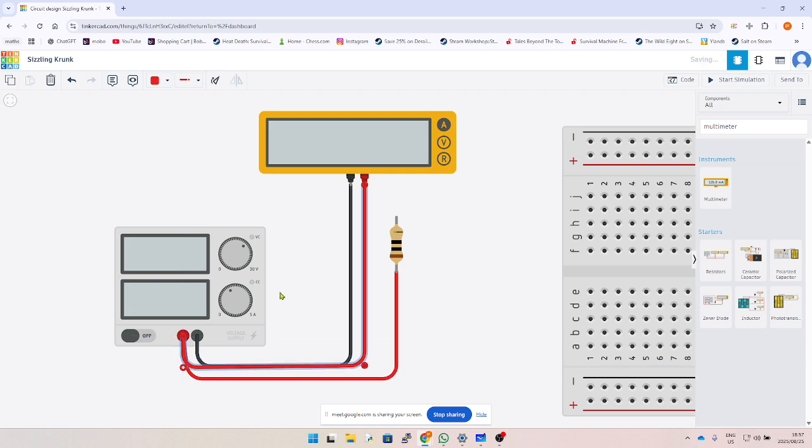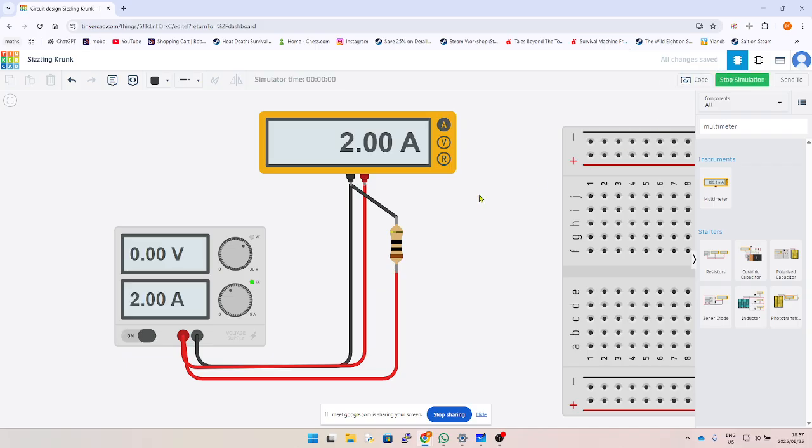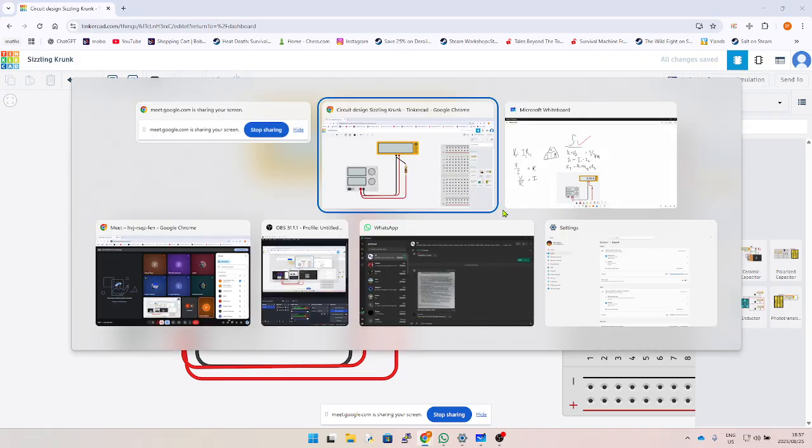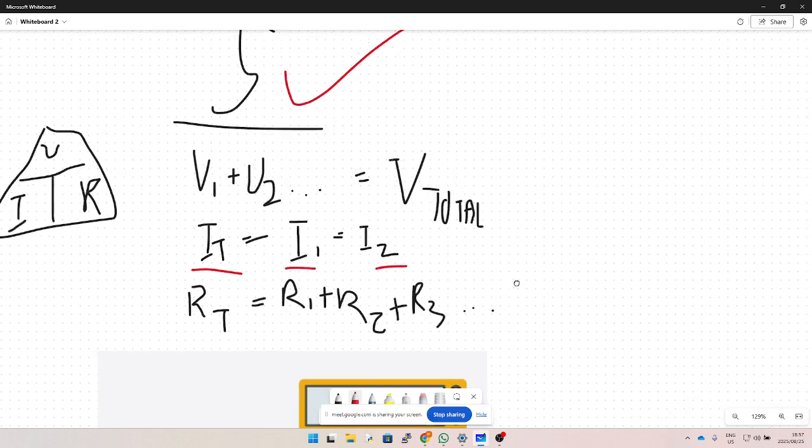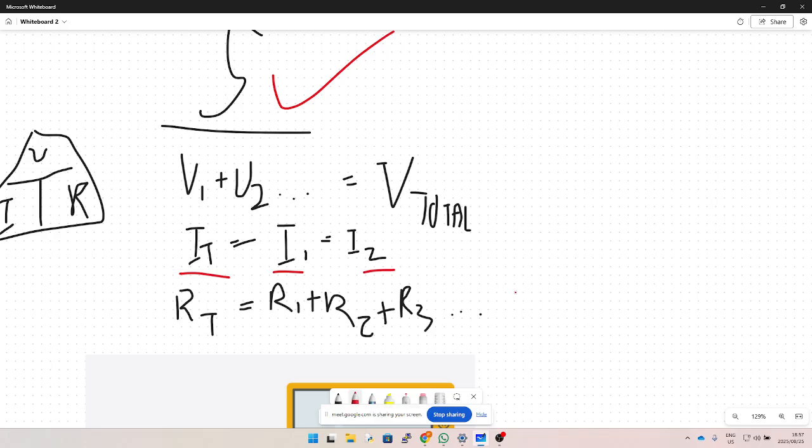According to Ohm's law for a series circuit, what's going to happen? What reading will I get? No reading. No, because even though the circuit is technically incomplete, you're still measuring amperage. Amperage in a series circuit, no matter where you measure from, it can be I1, I2, you still get the same amperage. No matter if I take a multimeter and connect it at any two points in a series circuit, the same amperage will be displayed. That's that formula.